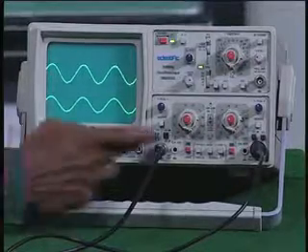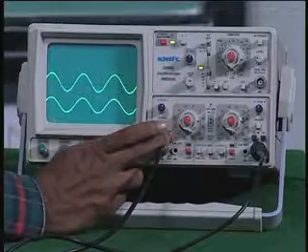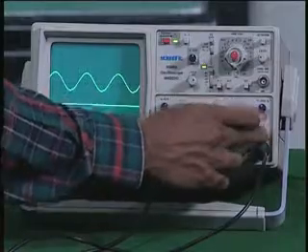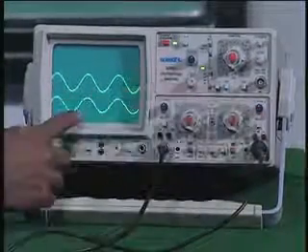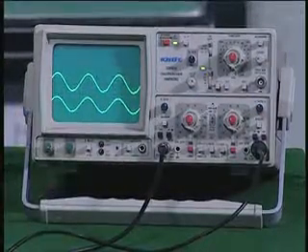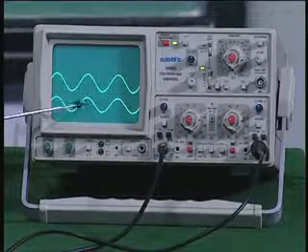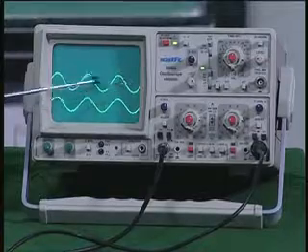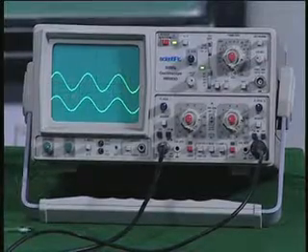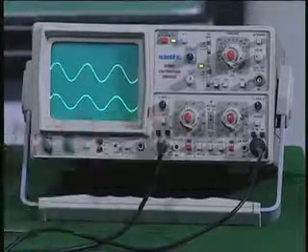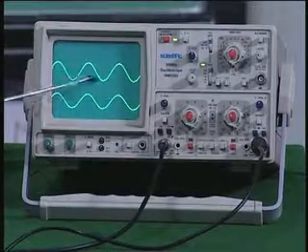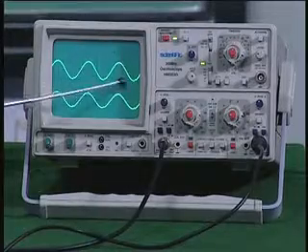That difference you can see by looking at the DC situation. So for example, I have a knob here which when I press, you can see this is now AC mode, this is DC mode, AC mode. So you can see in the bottom sine wave the AC is with reference to the ground, which is here. For the top one, you would find when I make it into DC, you find still the sine wave is there, and it is moved up to this line, the central line.